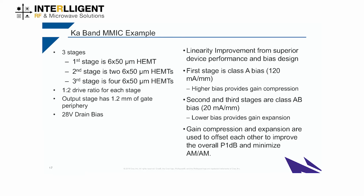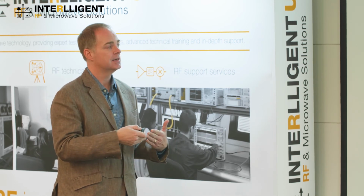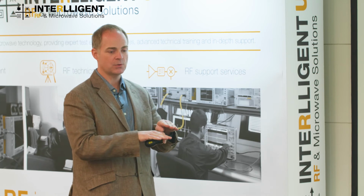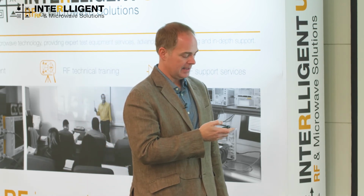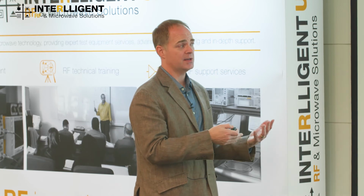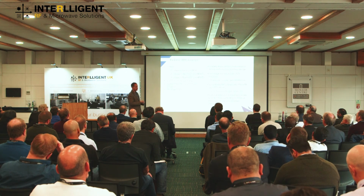So as I said, it was a 3-stage MMIC. It had a 1-to-2 drive ratio for all the stages, with 1.2 millimeters of periphery on the output, and it was run at 28 volts. The main things to take away from this is that there was a linearity improvement from both superior device performance plus some bias design that we did in this. The first stage was Class A, to keep it as linear as possible, and then the second and third stages were Class AB. And that lower bias provides for a little bit of gain expansion. So for what little bit of compression we did get, we were able to offset that. And that allowed us to get both better AM to AM and P1 dB than you would typically see on a 3-stage MMIC. At a lower frequency with our other processes, on a 3-stage MMIC, you would typically see the peak PAE occurring somewhere around 5 to 7 dB compression.